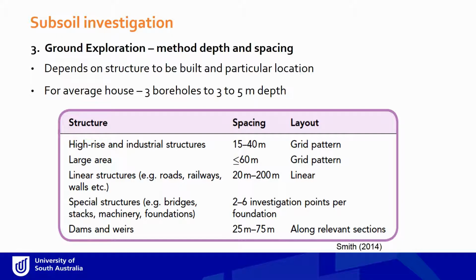See, if I'm going to build a car park, or if I'm going to build a bridge, these two projects will definitely have very different load carrying characteristics or load carrying requirements. So the spacing and depth we need to cover during a ground exploration has to be very, very different. So here are some of the examples or some of the guidelines to set up spacings, but they are just guidelines. Sometimes we need to do more closely spaced or less closely spaced, depending on the site, depending on the project as well.